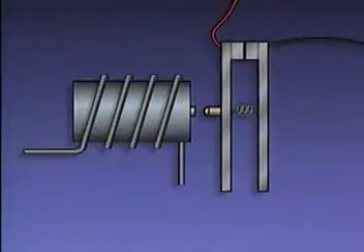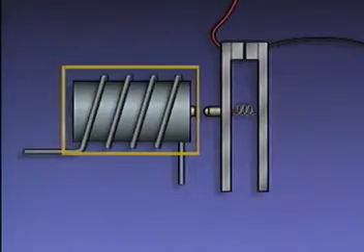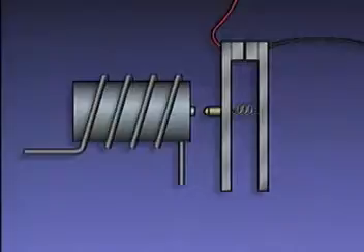You may also hear magnetic overload devices called magnetic overload relays. This simplified illustration of a magnetic overload device shows a coil around a metal core and a set of contacts. The contacts are held together by a spring. The overload device's coil is in the motor controller's power circuit, and the contacts are in the control circuit.